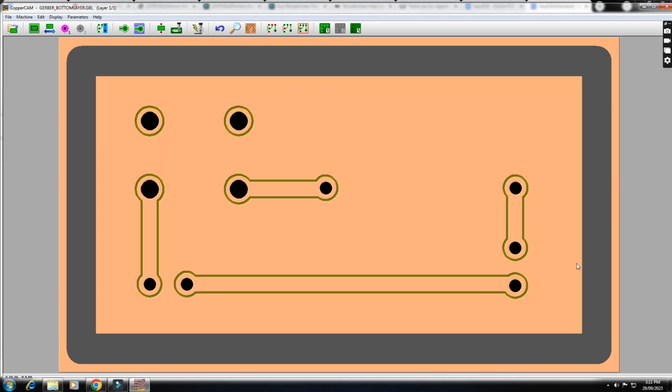So this is how your PCB is going to look. This will be the structure of your PCB. These points will be engraved. This green color is your substrate, and this is the track that I need. I'm not removing the entire copper. There is an option to remove all the other copper also, but it will take time. The easiest thing is to remove a single line around your tracks. That is what we are going to do.